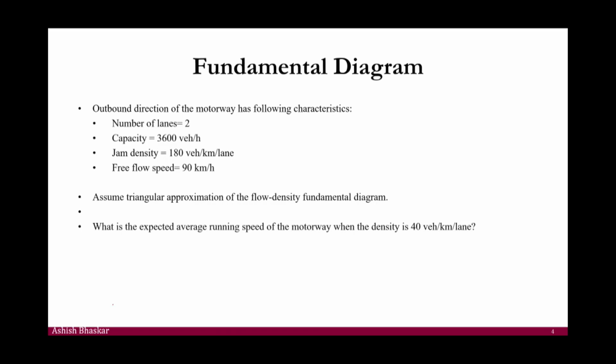So what you have to draw here is a fundamental diagram between, let's say, flow and density. Let's call Q here and density there. What is given to you is the capacity of the road, the maximum flow that it can reach. You know the capacity value, but please note the capacity has a unit.